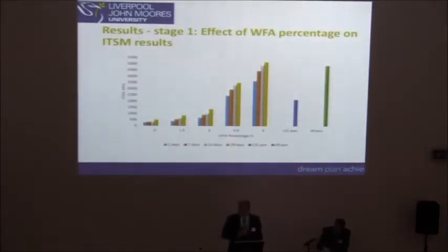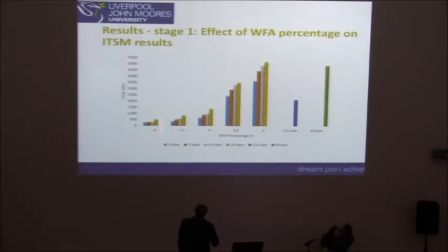This is our result. We have here 3 control mixes. This is the first one. It is cold mix without any additives. And we have 2 hot mixes, the soft hot mix and the hard hot mix. And we replace the mineral filler at 1.5%, 3%, 4.5%, and 6%.